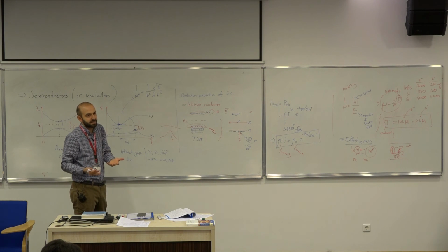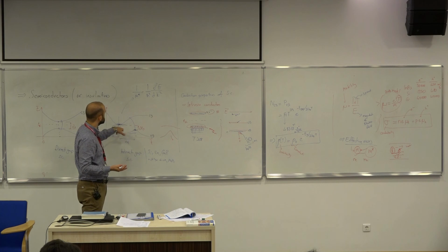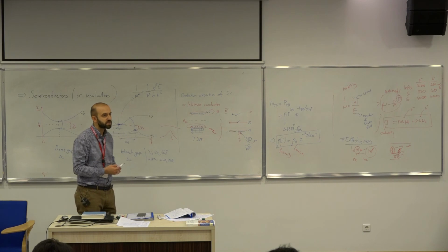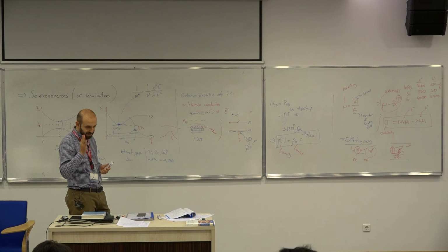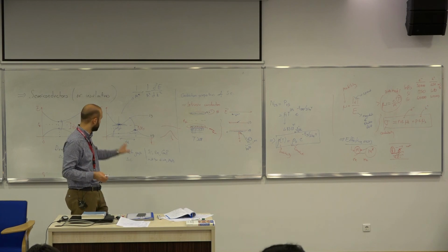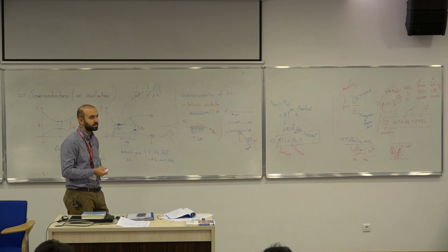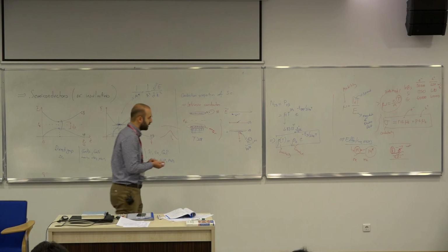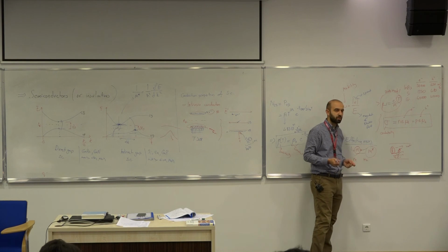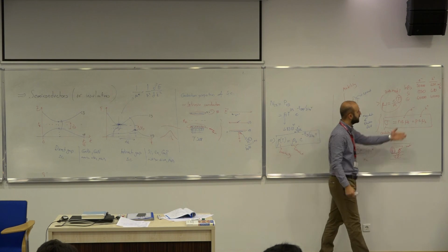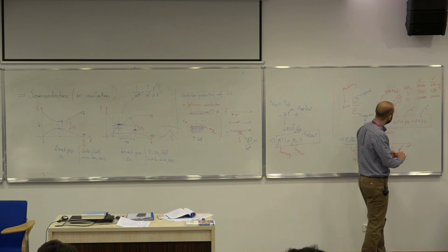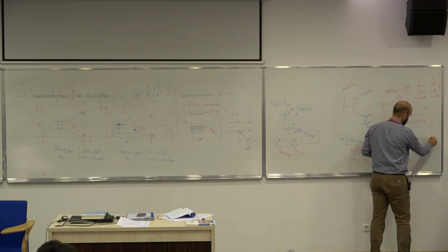So in a real case, the masses rarely equal each other. The mass of electrons is significantly different than the mass of holes, and you don't have a single mass for holes. You may have multiple masses for holes in the valence band. In reality it's more complex, but even for our case, you can safely assume that masses for holes and electrons are different. The exception, for instance, is graphene, because it has a completely symmetric energy diagram.